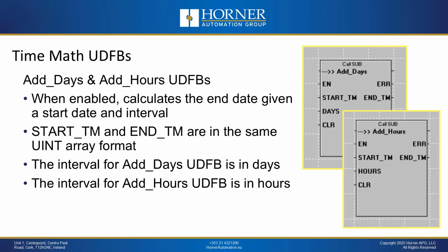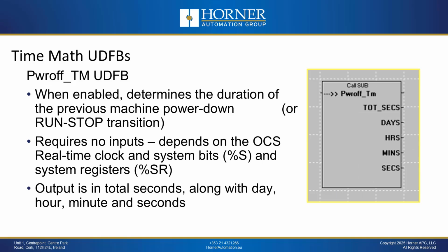We also have a couple of add functions, one for adding days to start time, another for adding hours to start time, and in both cases they give you the result in terms of date and time when the end time will occur. And then we have our powered off time UDFB. This is the one where you may want to react completely differently with your control algorithm, depending on how long a machine has been powered down.